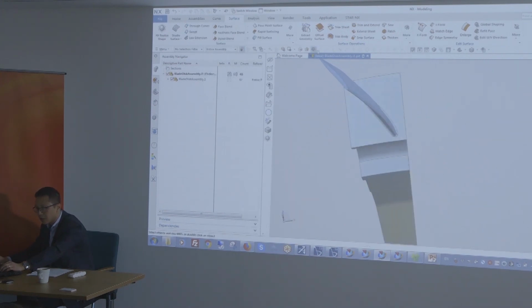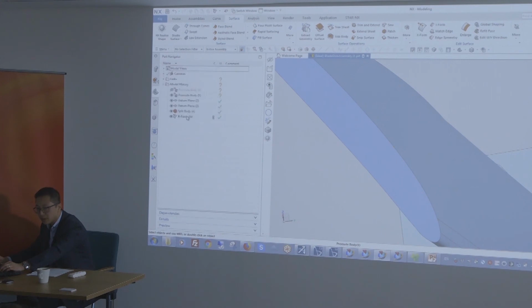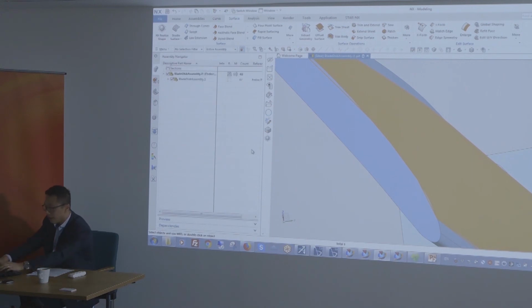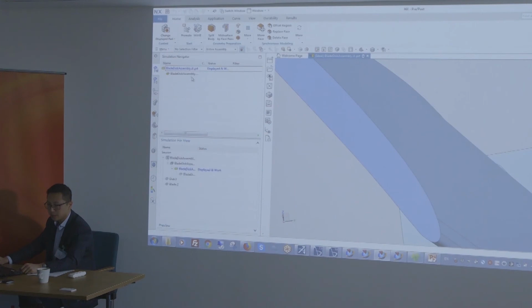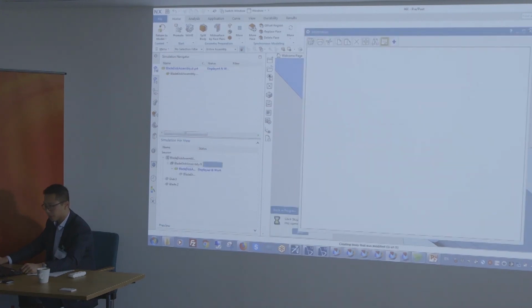Right, so for the geometry change, you see in the history tree that the feature has been saved. So you can always edit it, cancel it, modify it. Okay. Then we'll just go back to the FEM, which is our mesher. You'll get a notice that something's changed. Maybe have a look at your geometry, see if it needs to be updated.